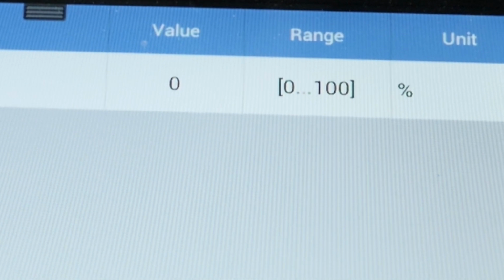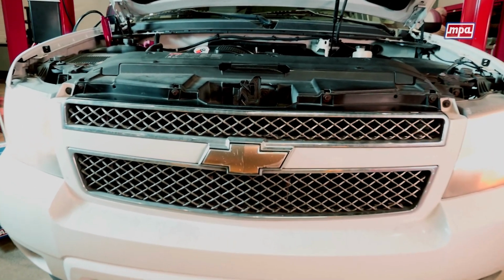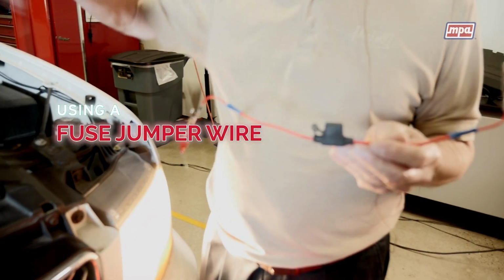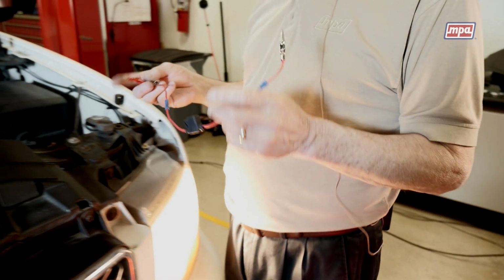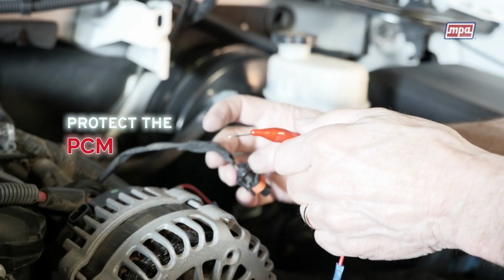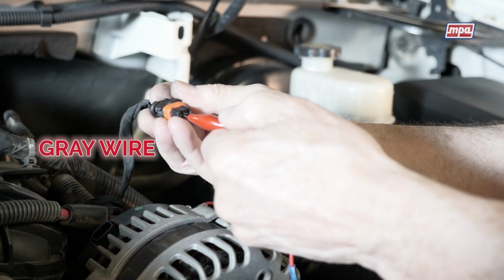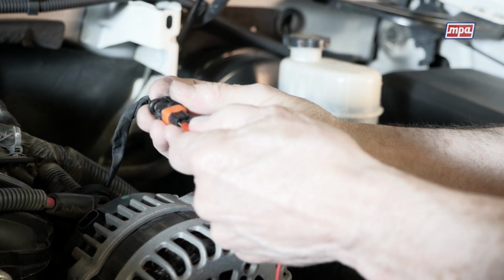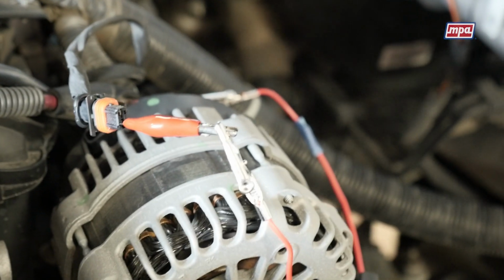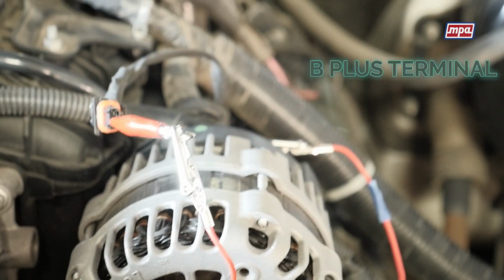Now we can also do another step to further verify the integrity of that circuit. Using a fused jumper wire, we have a 3-amp fuse in this inline jumper wire here, in order to protect the circuit and protect the PCM. We can back probe that F circuit, which in this case is the gray wire, with a very small probe, and then connect the other end of our jumper wire directly to the B+ terminal of the alternator.